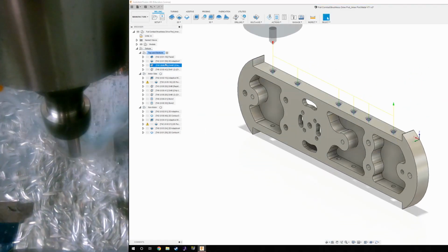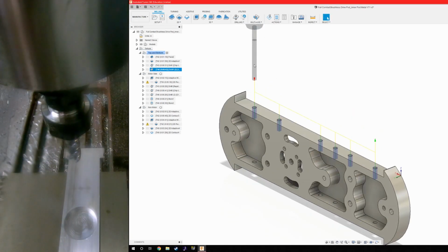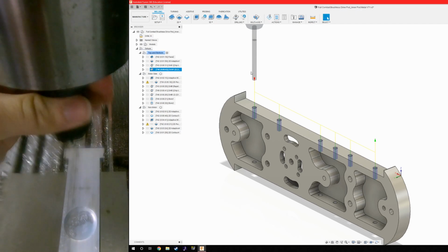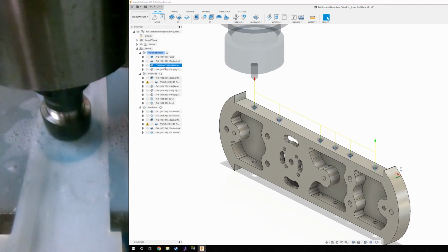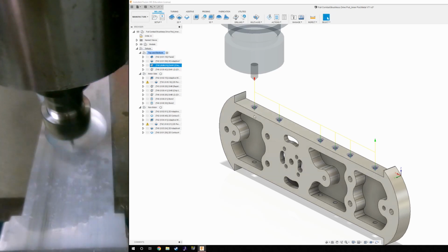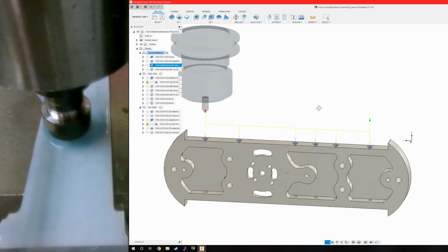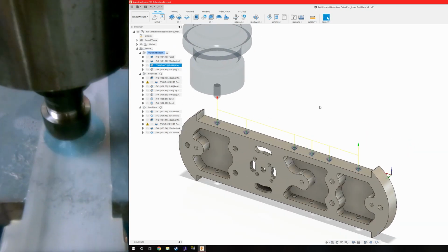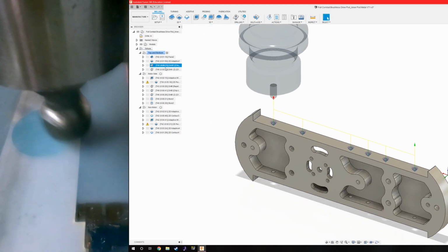The reason I have to spot drill first is because jobber length bits are quite long compared to their diameter, so they're not stiff enough to stay on center when you just straight drill into a flat piece of material, so you really need a drill point already in the material. Oftentimes if you're working by hand you might just punch it in with a center punch, but in the case of CNC there isn't really a good way of doing that other than just using a tool that has an angle to the tip.